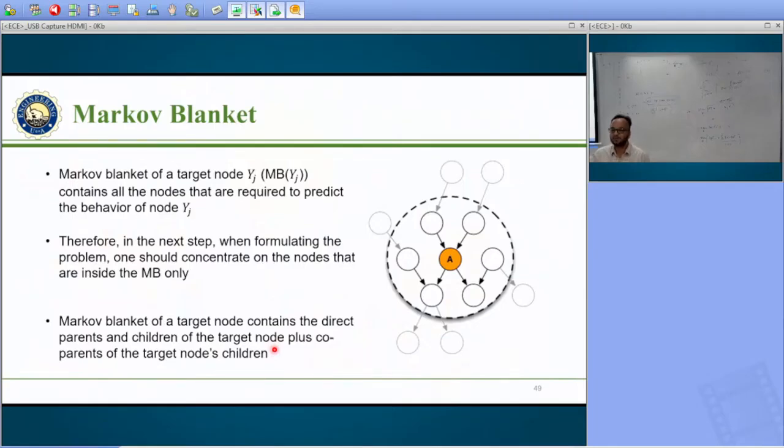Wireless sensor networks. So let's suppose you wanted to keep multiple sensors, like on a jet engine. There you use sensors at multiple locations to measure the turbine temperature, the inlet temperature of the fluid. How many sensors you want to use and where to place them is a critical question. If I know the network structure of these variables, I can reduce the sensors. I don't need to put sensors around this particular location, only around these particular variables, because they carry a good amount of information, and for the remaining I don't need to put any sensors. So you can reduce the dimension.